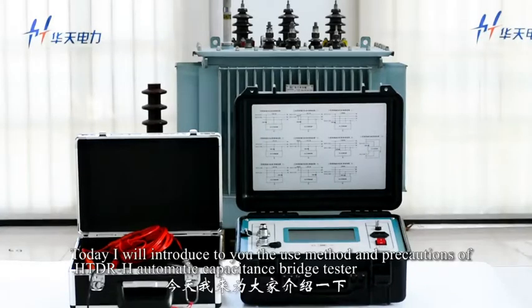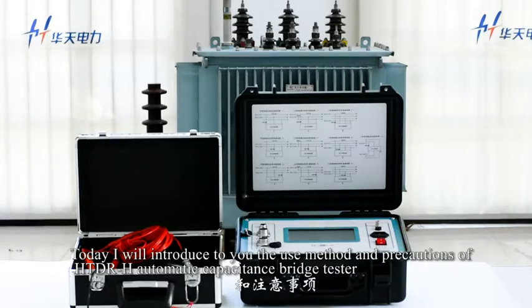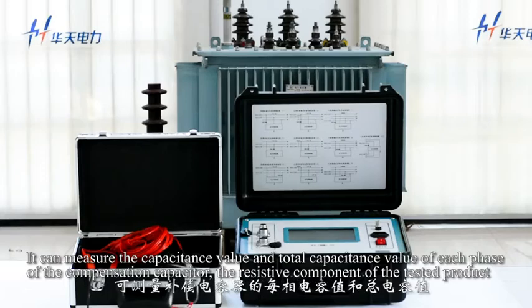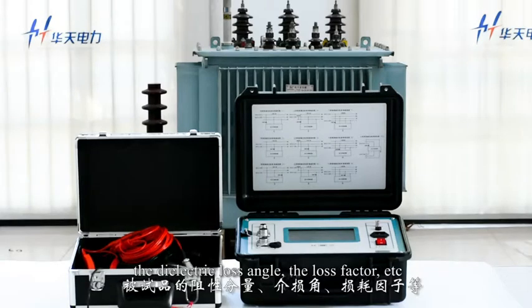Today, I will introduce the use method and the precautions of the HTDR-H automatic capacitance bridge tester. The HTDR-H capacitance bridge tester is an instrument for measuring high-voltage shunt capacitor banks and the reactors of reactive power compensation devices. It can measure the capacitance value and the total capacitance value of each phase of the compensation capacitor, the resistive component of the tested product, the dielectric loss angle, and the loss factor.